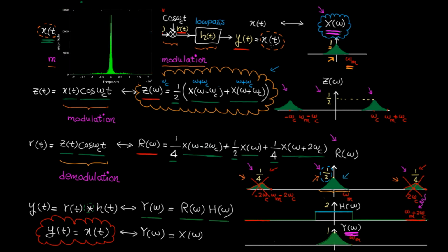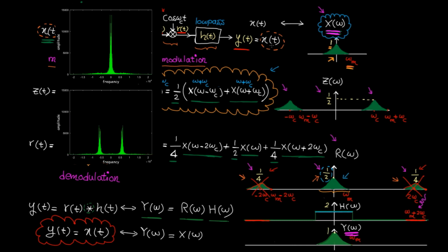Here's the song in the frequency domain. Now I modulate it with a cosine function. Here's the modulated song in the frequency domain. As you can see, modulation with cosine function shifts the frequency content to the higher frequencies in both directions. Also, the amplitude of each copy is half of the original song. Let's listen to the modulated song.